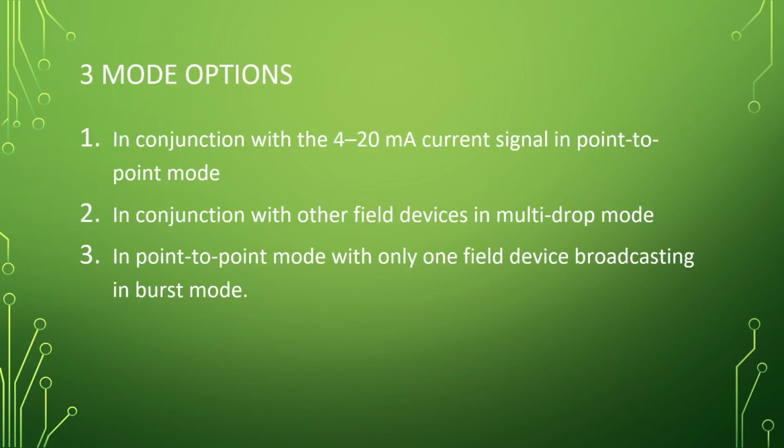So, we have 3 mode options. You can do it in conjunction with the 4-20 milliamp mode. You can do it in conjunction with other field devices in a multi-drop mode, or you can do it in point-to-point mode with only one field device broadcasting in burst mode.